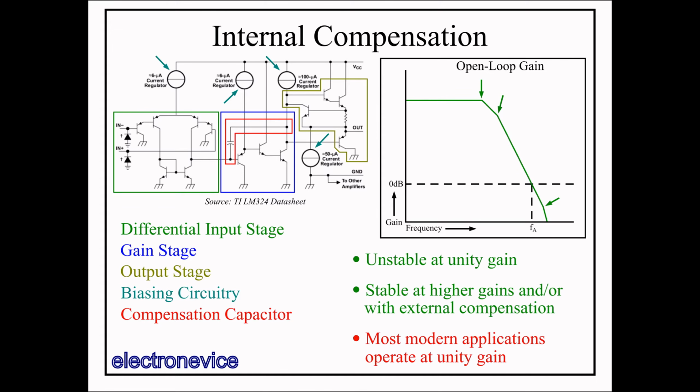You can see it prominently displayed on the LM324 equivalent circuit from the input of the emitter-follower stage to the output of the common emitter stage, which marks the input and output of the overall gain stage respectively. This changes the transfer function dramatically, moving one of the poles to a much lower frequency and moving the second pole to a higher frequency. This is the dominant pole configuration we're familiar with, and the phase from the additional poles only coming into play right near the 0 dB gain crossover point.